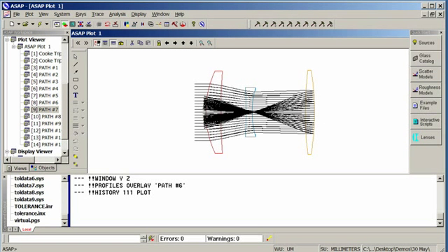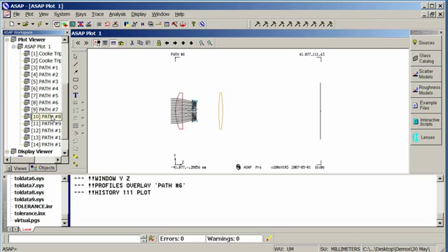In this case, what we see is our Fresnel reflection off this surface is forming a significant image within the optical system. Now, if this is a photographic objective and I'm just taking pictures of the Tucson scenery, this probably isn't a problem. If this is being used in a high-powered laser design and I have concentrated energy in this region, it could pose a problem. This is, again, one of the reasons you'll need to do an analysis within ASAP. And again, that's the basic paths that we have available to us.